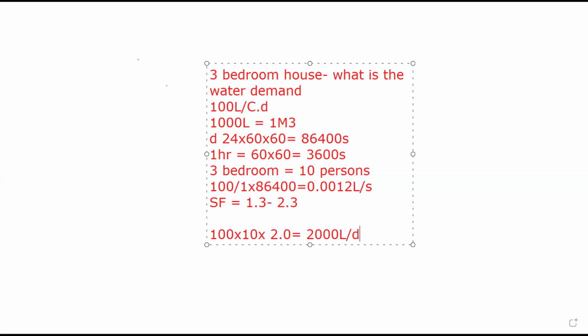But a poor designer will design for 2 hostels, and then when you build the 3rd hostel, there's no water in that hostel, because the pipe sizing is poor. If you use 3 inches pipe as against 5 inches pipe, it will only take 2 hostels, but the 5 inches pipe might have taken extra 3 hostels. I'm just giving you an idea to see why sometimes Mr. A has water, Mr. B does not have water. It's a consequence of poor design. And that is why this training is important.